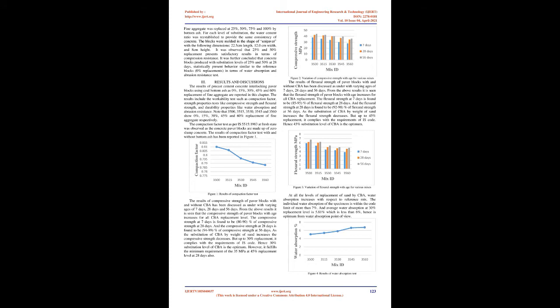Manufactured sand as fine aggregate, and crushed stone of 20 mm maximum nominal size as coarse aggregate, were used for the study. It was observed that the strength reduced marginally on the inclusion of bottom ash in concrete. The water absorption of bottom ash concrete at 28 days curing age increases approximately linearly with the increase in replacement level of sand, and it decreased when microsilica was added to the optimum mix.